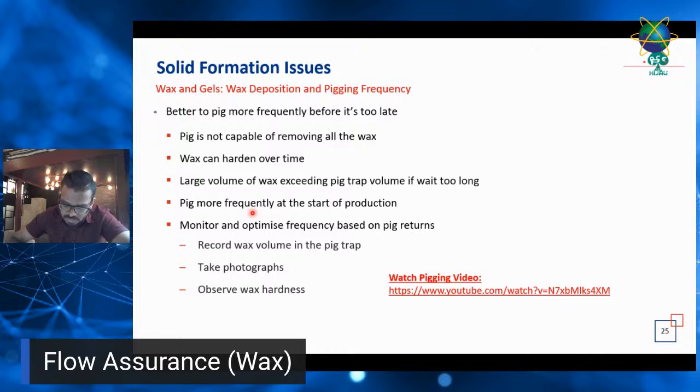And usually wax is an issue during early life as compared to late life. The reason is that at late life there will be water breakthrough, and so your water cut will be higher. Since your water cut is higher, your water will tend to hold more heat, because the heat capacity of water is higher, so it can contain more heat. Therefore, you will not foresee much wax issue towards the late life of your field.